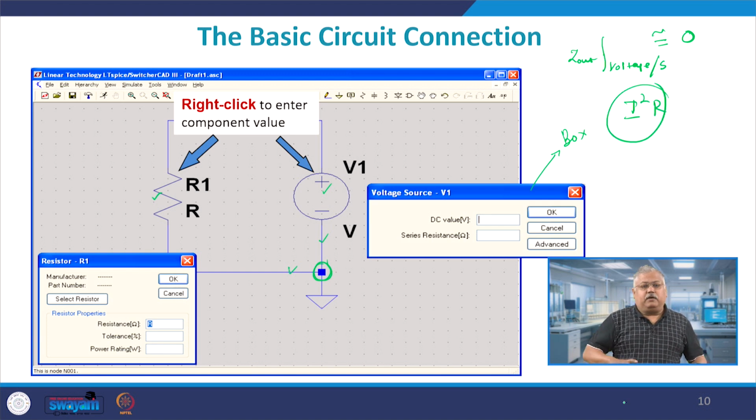So, why is this power important? Let us suppose you are doing a high voltage simulation here, or maybe let us say a power electronic simulation here, where the currents are very large, then I squared into R is also very large, and therefore, if your output power dissipation is much larger than the maximum power rating of the device, the resistor will actually burn out.